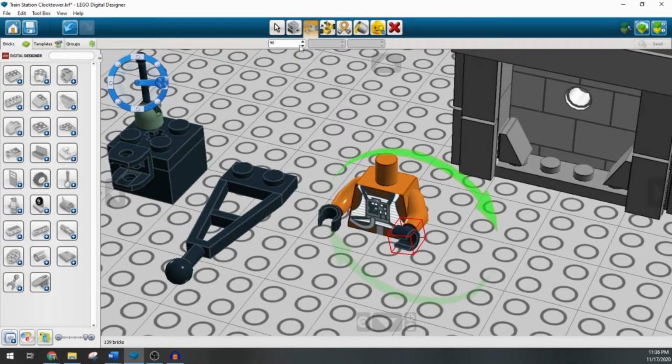Option number 2 is the window itself. You can manipulate things in the window by increments of 1 degree with these little arrows. You can go in directly and go even further down, so I could say like 55.25 degrees. So it'll give you increments of a quarter degree. I actually haven't tested how low this goes.